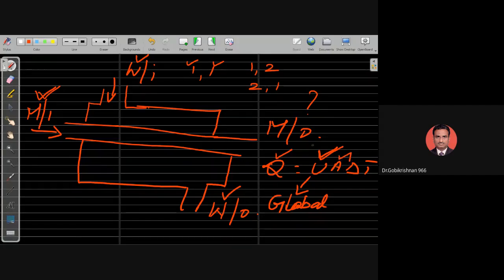Heat transfer area is nothing but the contact area between the hot and cold fluid. If the contact area between hot and cold fluid is more, the heat transfer rate will automatically be higher. And the del T is the temperature difference between the hot and cold fluid. But if you take a shell and tube heat exchanger, the del T is not a constant. Del T is the temperature difference between hot and cold fluid. From the inlet to the outlet, if we check the temperature of both the fluids, it will be changing.